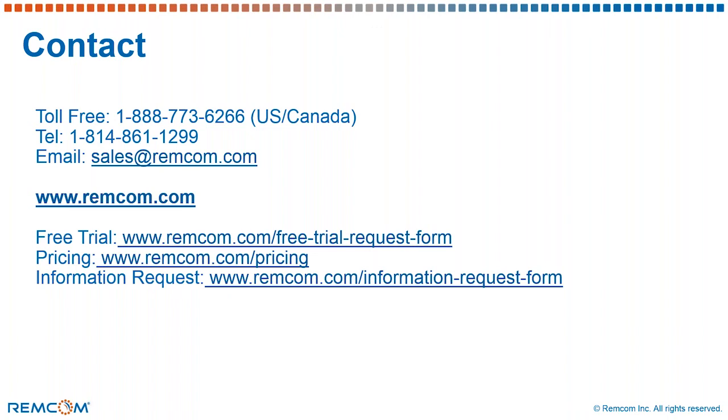There's a question about the beamforming techniques. We use maximum ratio transmission and zero forcing and other beamforming techniques. We chose to use MRT and ZF because they represent two ends of the spectrum, either maximizing the power to each device or minimizing interference to other devices. And when looking at the reverse, MRT is also equivalent to another technique called maximum ratio combining for the uplink. But there are other beamforming techniques such as minimum mean square error, and there are certainly many other MIMO techniques as well. So these were just intended as a sample of different potential possibilities.